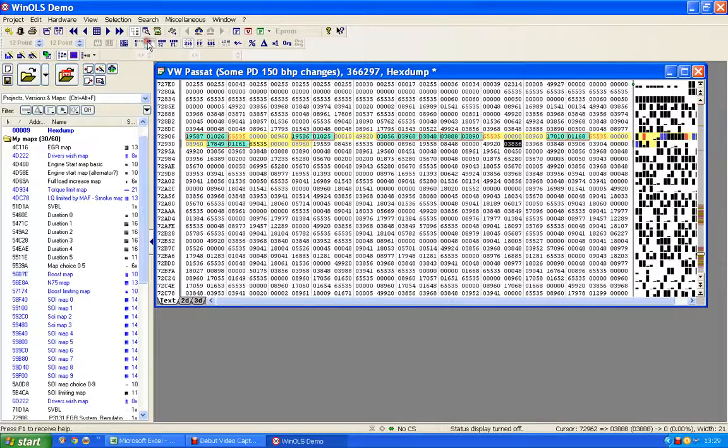Now just go back to 16-bit so that we're looking at what we were looking at originally. Let's assume that we are now correct. Obviously it'd be very simple to find out, wouldn't it? Because I load this file into my car, which already had EGR errors, or didn't. But I load it into my car, let's say, and I unplug a connection to the EGR actuator, which will throw up instantly faults about the fact that the line is unplugged.